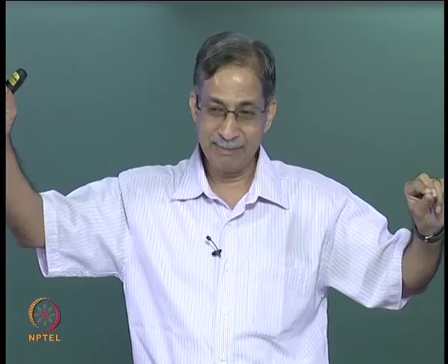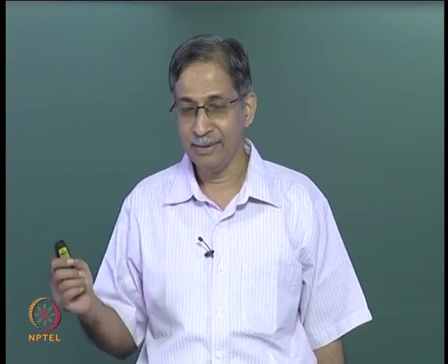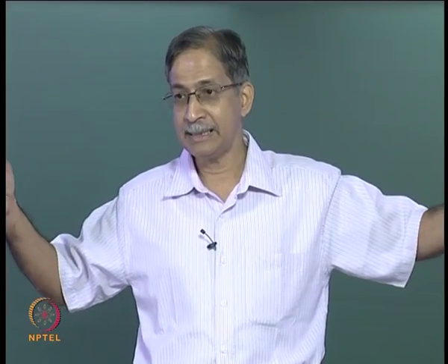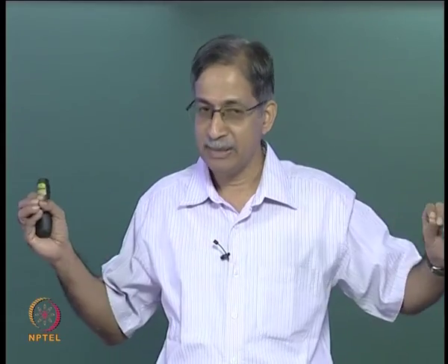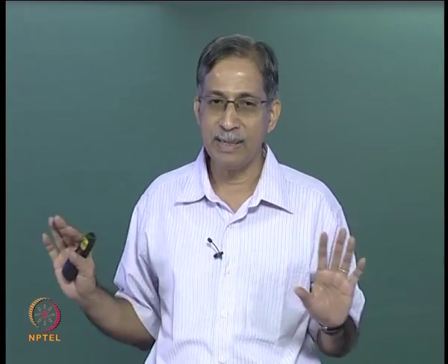So you have differential settlement in that beam, and if the beam is not long, 6EI delta by L squared is the kind of fixed end moment that you will get. That is a huge moment. If you work it out, it is very large, but when you do the frame analysis, you will find you end up with a much smaller moment. But unless you can do that distribution through an analysis, you can't prima facie say whether it is negligible or not. So when you have more members coming into play and more flexibility in the structure, you really do not have to worry too much about indirect loading. It kind of takes care of itself.